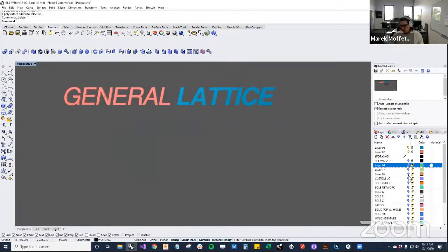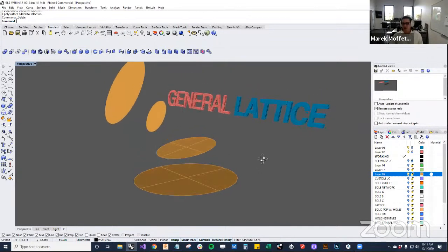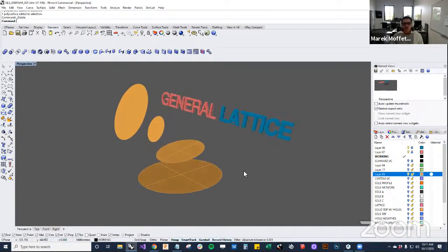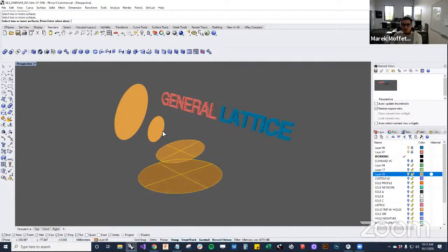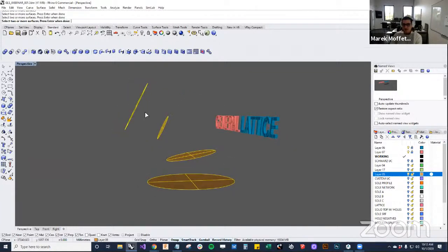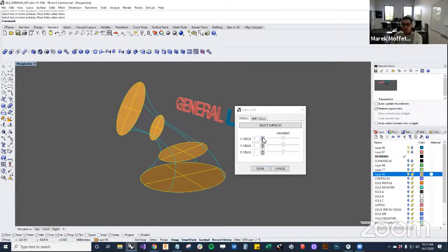Great. So with that, I'll move to a next example of how to use our tool here. Previously I used just a pair of surfaces, so just two, but very similar to the Rhino Loft command. If you put in more than two surfaces, you'll get curvature with trying to interpolate between those. And so I can show that by selecting the surfaces in the order on which I want them to generate, and we'll get our wireframe preview.